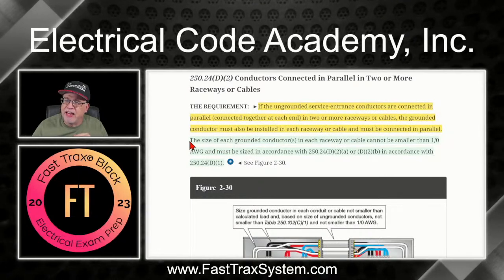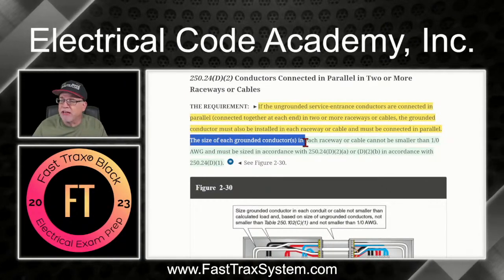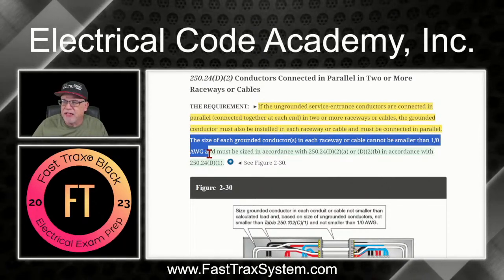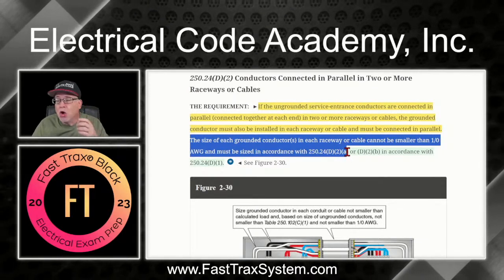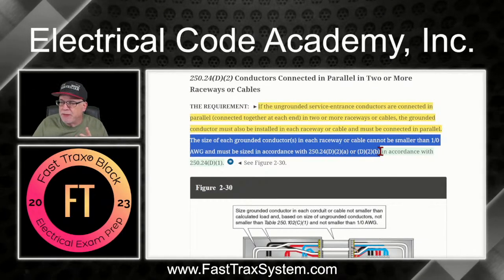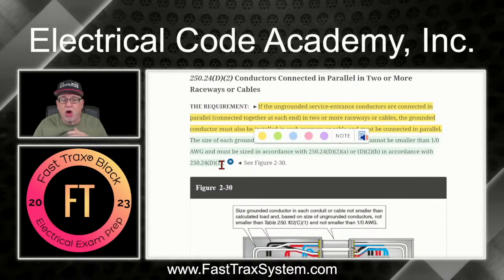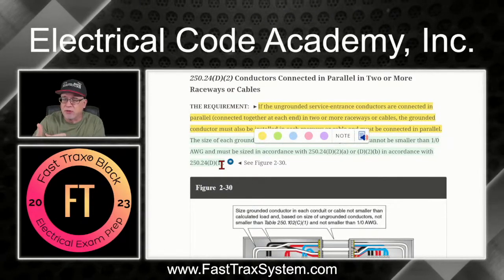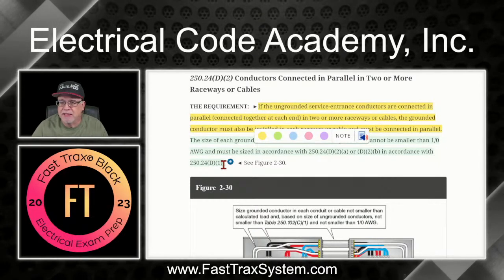It goes on to say that the size of each grounded conductor in each one of those raceways or cables cannot be smaller than 1/0 and must be sized in accordance with 250.24(D)(2)(a) or (D)(2)(b), okay? And all of this is in accordance with 250.24(D)(1), and all (D)(1) is doing is sending you to 250.102(C)(1), ultimately to do the final selection of the minimum size grounded conductor, okay?